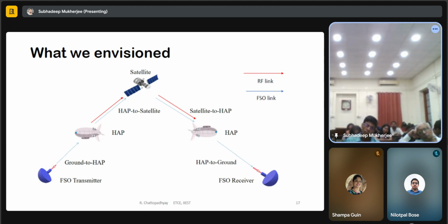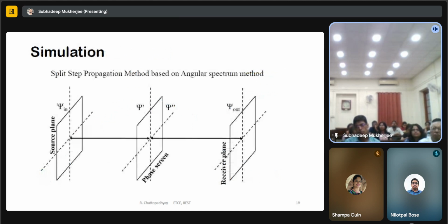So we need a correction system where we predict the channel through some probe beam and figure out the noise in the channel itself, and then we pre-code the beam with the conjugate of the noise so that the channel itself acts as a corrected system. So here the channel will act as a deformable mirror, and instead of having a pure beam, we are actually uploading a distorted one. So this is what is called a pre-correction algorithm.